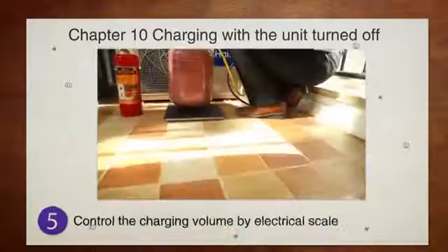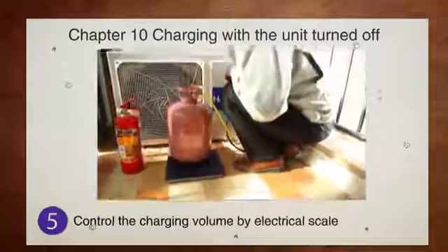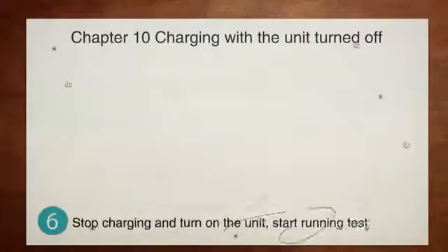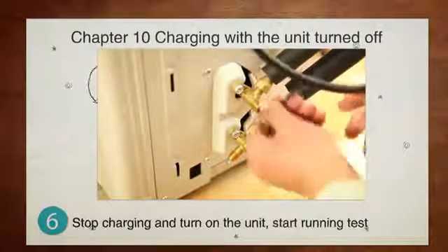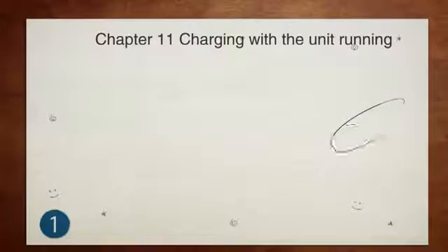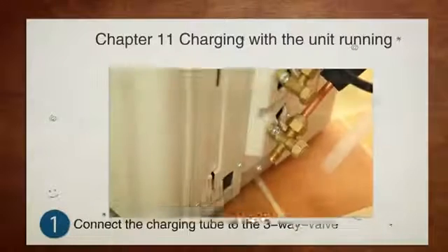Number 5. Control the charging volume by electrical scale. Number 6. Stop charging and turn on the unit. Start running test. Chapter 11. Charging with the unit running.